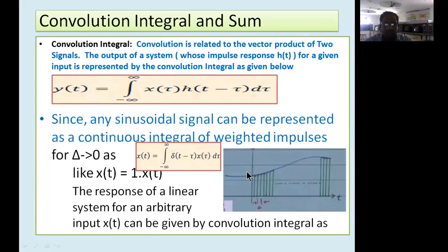So at last, the system is actually doing the process called convolution. So in this convolution, what is exactly happening? In convolution, the signal x of t is simply getting multiplied with the impulse response of the system under consideration. We are simply getting the effective area after multiplication of the signal with the transfer characteristics of the function